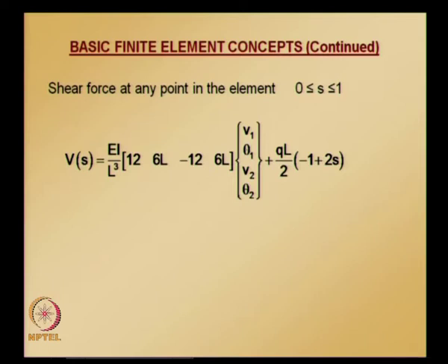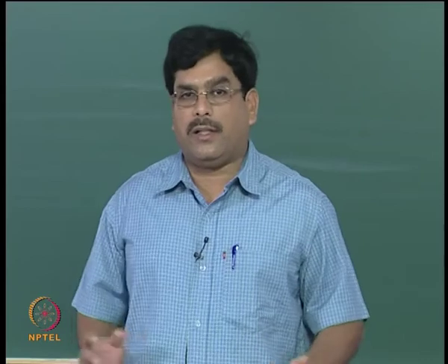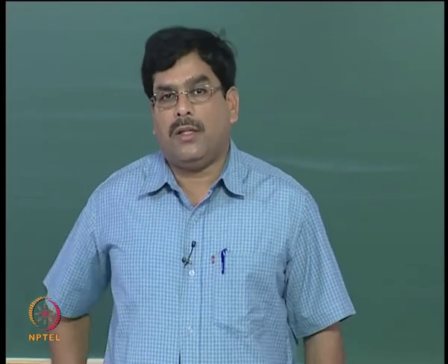The first term is nothing but interpolation of the nodal values as you do for any other problem with concentrated loads, and the second term is the correction term for the distributed load case. And as I mentioned, all these correction terms correspond to a fixed beam with uniformly distributed load, and if you have some other loading you need to add the fixed end moments corresponding to that loading, imagining that each span of the continuous beam is fixed.